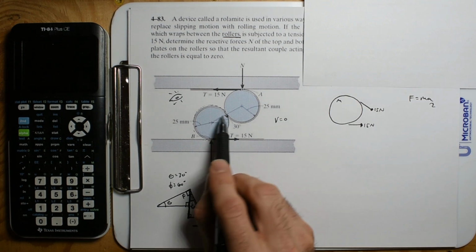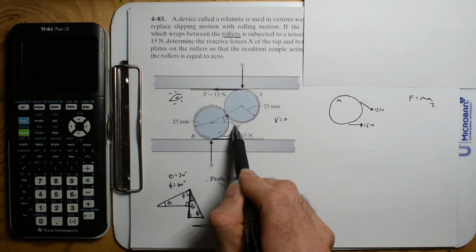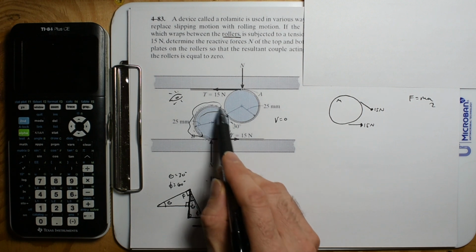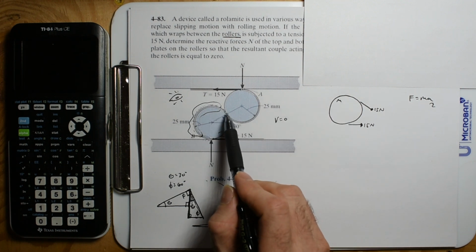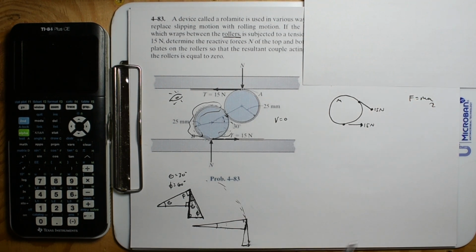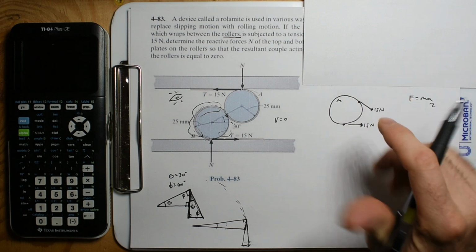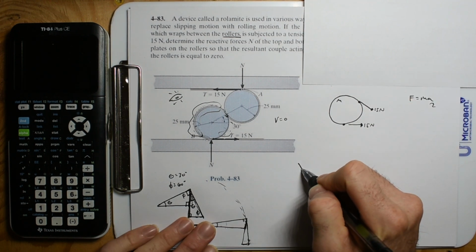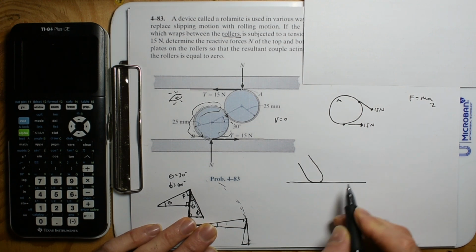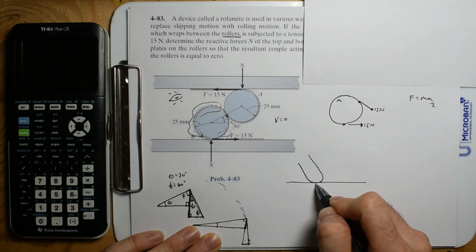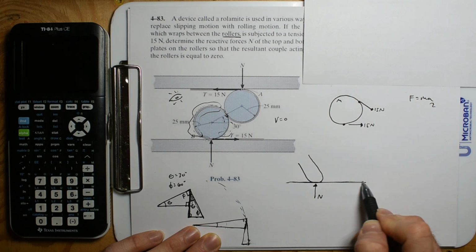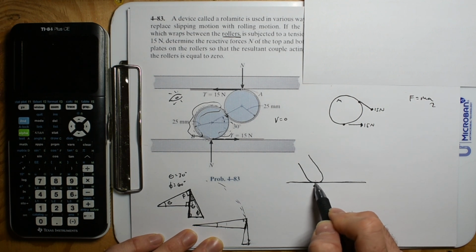Because if I look at this circle, all through here, I'm not going to have any other forces. There's nothing touching this side and that side of this roller. But I do have a contact point there, and I do have a contact point with the ground. So anytime that you have a contact point, here's a chair leg with a rounded end, and then it's just on the floor. What's going to happen is that you're going to have a normal force that's perpendicular to the surface.